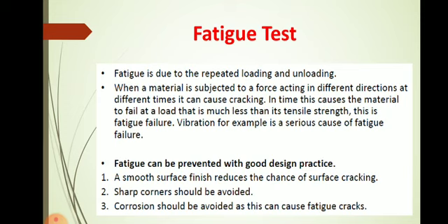We have already seen fatigue is due to repeated loading and unloading. When the material is subjected to force acting in different directions at different times, it can cause cracking. In time, this causes the material to fail at a load that is much less than its tensile strength. This is the fatigue failure. Vibration, for example, is a serious cause of this fatigue failure. Yes, vibration is also a major cause of fatigue failure.